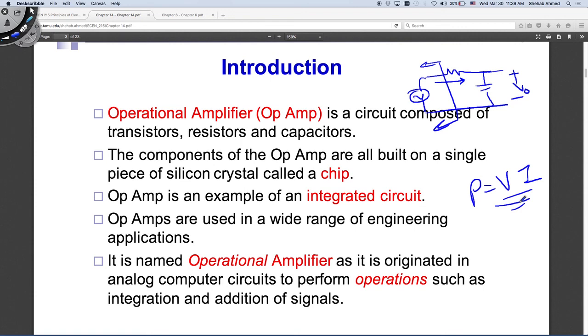And they're measuring that with a sensor. This sensor has an output voltage. This voltage you would like to measure, but this sensor is actually not supplying power, right? So you would like to measure the sensor's voltage, but the sensor is not capable itself of supplying a lot of current, right? So I want you to differentiate between voltage and current, right? The sensor is going to generate a voltage that is proportional to a physical phenomenon, and you would like to measure that voltage, but the sensor is not able to supply power. It's just sensing a signal and creating a certain voltage.